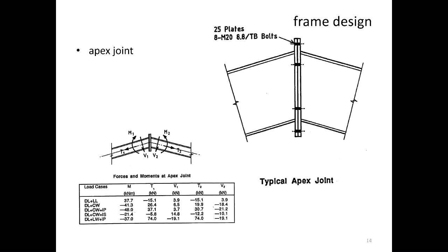So that is why you can see this is designed as a moment connection, because I've got 2 holes at the top, 2 holes at the bottom, and 4 in the middle. Can you see that? That's the end plate. So that will be another end plate here. So that end plate there is one of these, and you have another one which forms the V shape.